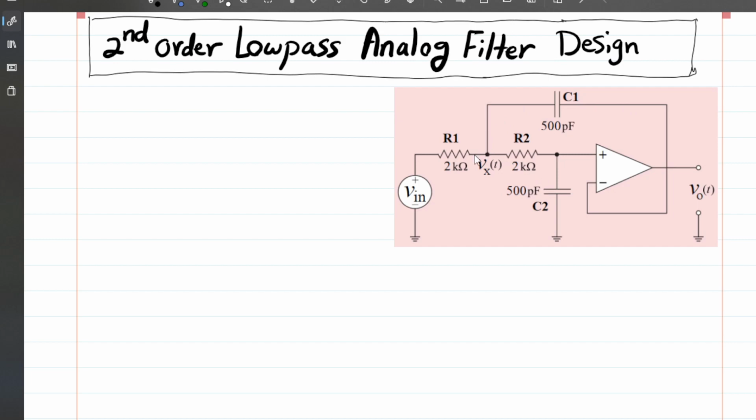So in such a scenario, at super low frequency, this voltage is directly connected to the input positive terminal of the op-amp, and there is no way for current to escape, because we are assuming this is an ideal op-amp. It means the input impedance is infinite as well. So there is no way for current to flow at super low frequencies. Therefore, the current drop across R1 and R2 is negligible, as this Vin appears exactly on the positive terminal.